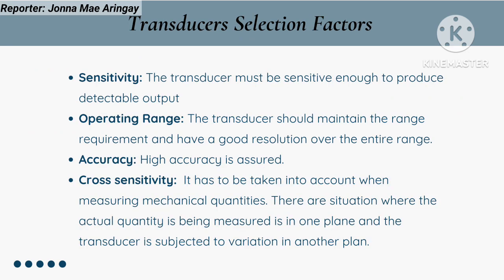The following factors are to be considered while selecting a transducer for further applications. Sensitivity. The transducer must be sensitive enough to produce detectable output. Operating range. The transducer should maintain the range requirements and have a good resolution over its entire range.